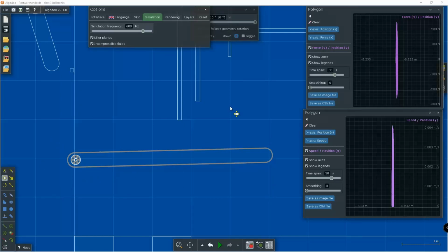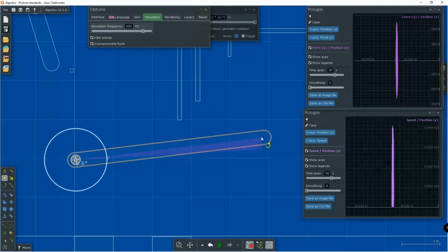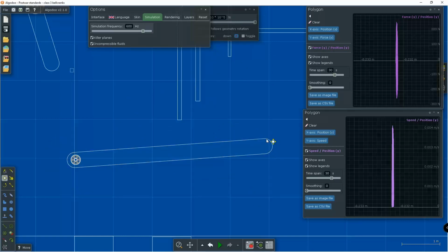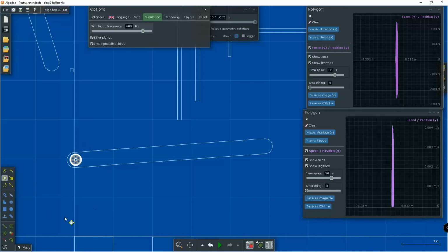If within our reference frame one side here is fixed, then we can call this a fulcrum, and we can have either the effort or load both on this part. Now, technically, in the case that it is merely providing a circular motion constraint, then the concept of effort and load don't really apply. But in the case that this thing that we previously called the fulcrum is actually moving with respect to another frame of reference, then we can regard this, or either end, as being either the effort or the load, and then there would be no more fulcrum.